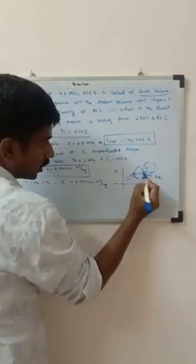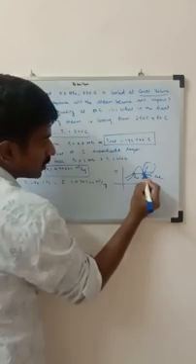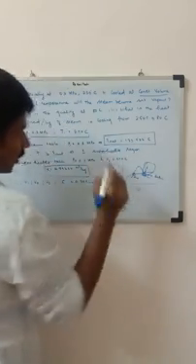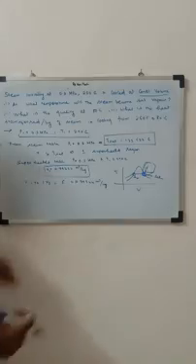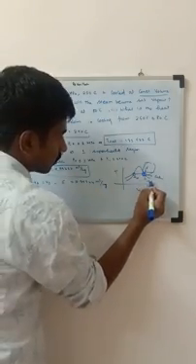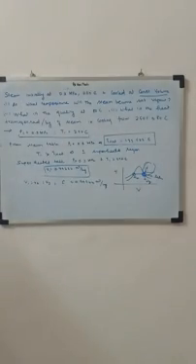So he is asking at what value of temperature the steam will become saturated vapor, at least this point. So what is this point? We know that this point is Vg. So what are we going to do? We are going to go to the steam table and calculate the value of Vg for the given value.